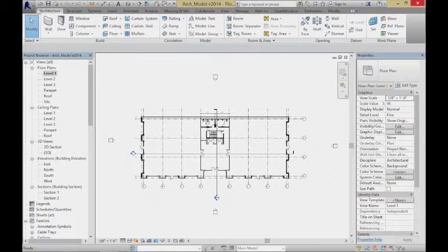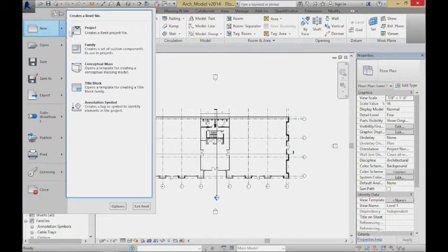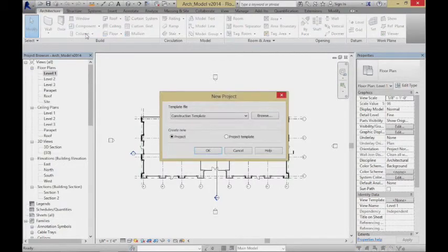In fact, I was going to advocate that you create a new MEP file, because it's probably better to start with the mechanical template as opposed to the architectural template. That way, all the elbows and connections and ductwork sizes are already in there. It's a little bit easier to work with. So go ahead and just start with the mechanical template. We'll go from there.